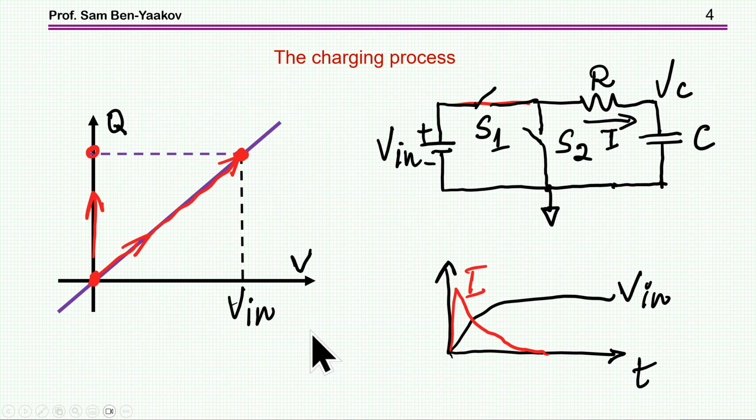voltage. So let's start with a very simple case in which we are charging a capacitor from a voltage source. I'm showing here two switches. I'm turning on this switch, and this process now charges C eventually to V in, and I'm assuming that this process is ending at this point. The voltage is rising and approaching V in. The current starts high because the full voltage is on the resistor. I'm assuming, of course, that the capacitor has zero voltage at the beginning. I'm going to discuss other situations later on. So the current goes to maximum, and then it drops off exponentially.